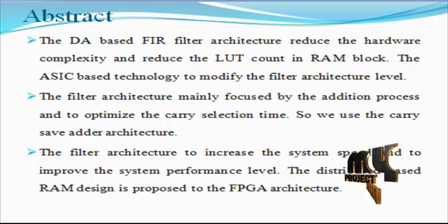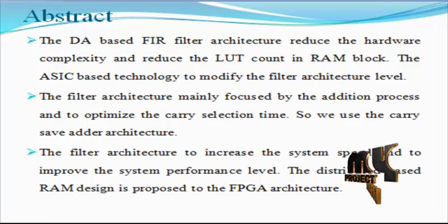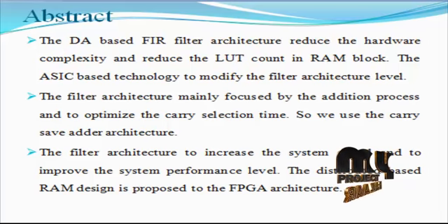Conventionally, for reconfigurable DA based implementation of FIR filters, the lookup table based DA units are required to be implemented in RAM, and the RAM based LUT is costly for ASIC implementation. Therefore, a shared LUT design is proposed to realize the DA based computation, instead of using separate registers to store the possible results of partial inner products for the DA processing of different bit positions. Registers are shared by the DA units.